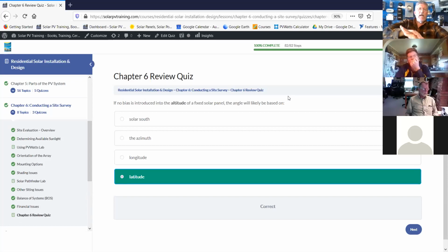So you would think that would be the ideal orientation for your solar panel, but it's not, because the days are longer in the summer and shorter in the winter. And also we tend to have more sunlight, more clear days in the summer. So you would typically have a summer bias to your pitch. So even though on average it's 40 degrees, because the days are not uniform in length and sunshine is not distributed uniformly, it's biased to the summer, you would tend to lower the panel's angle by 15 degrees, which is referred to as a summer bias.